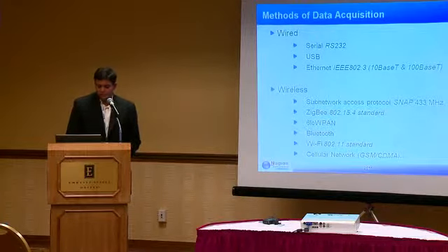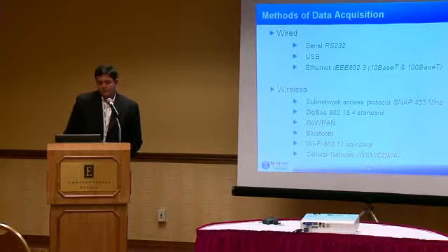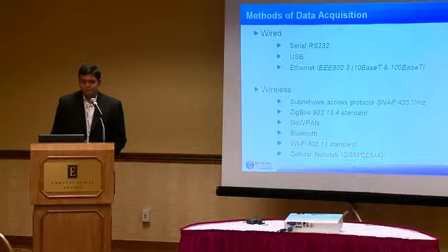And with the Wi-Fi, we all love it. We all use it all over, and it's a well-known standard. We use the 802.11b in most of our products because although you may wonder, when G and N are there, why we still stick to B, the reason is B takes less power. So if you want a battery-operated application, B does a better job.